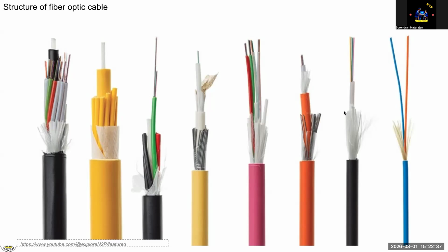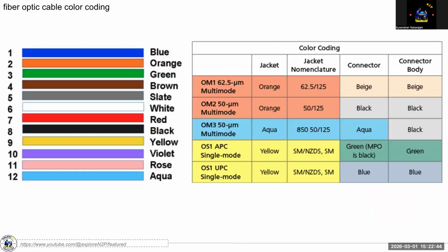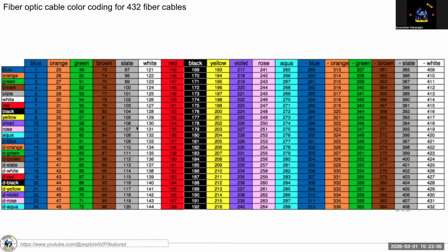See, only two are there here. Usually 12 are there, and all those 12 fibers are differentiated using color codes. Usually they pack the fiber in ranges of 12. It starts with blue, with unique colors, the color coding, same like our boys. They follow it for 12, then for another batch it will follow the next pattern. I will show you the color coding.